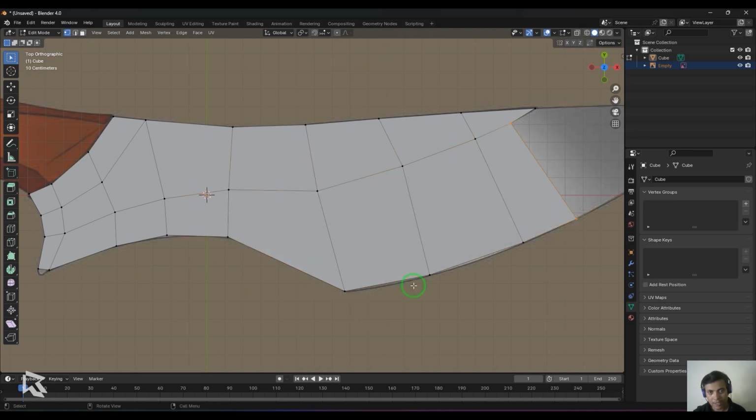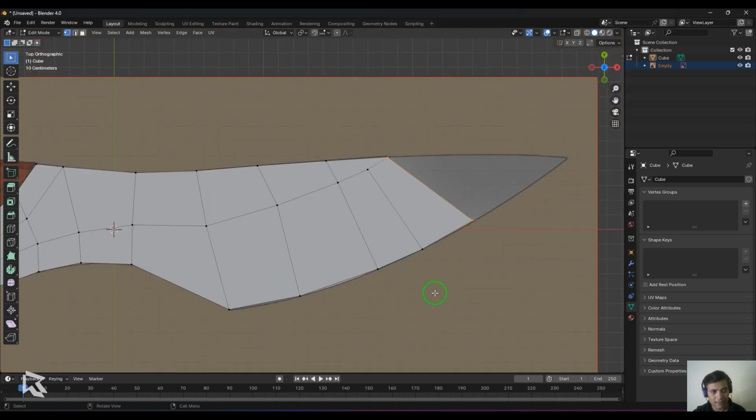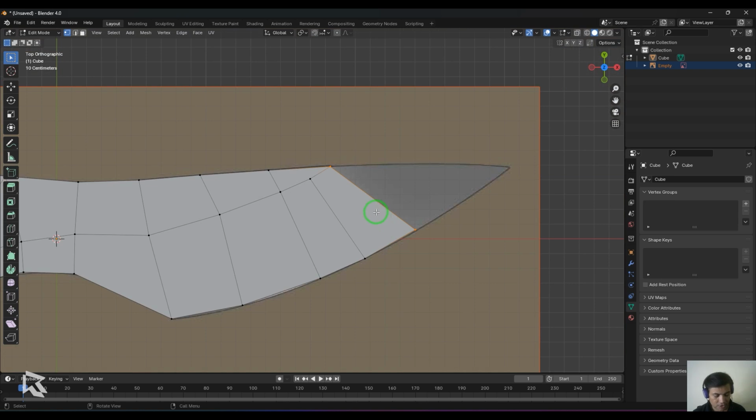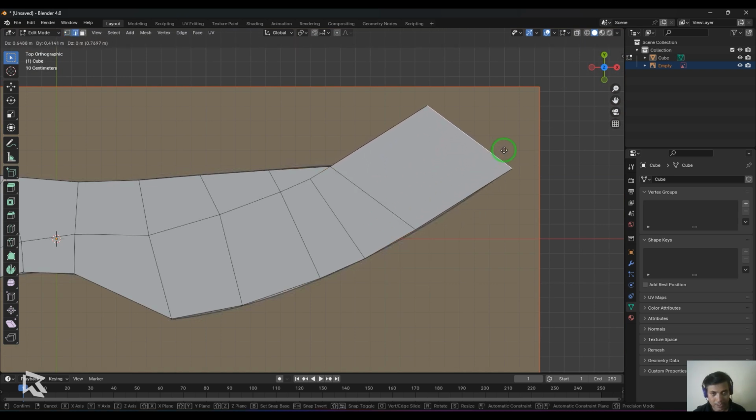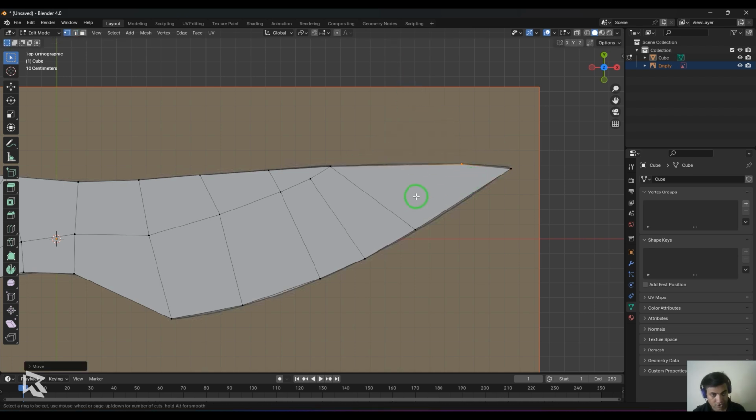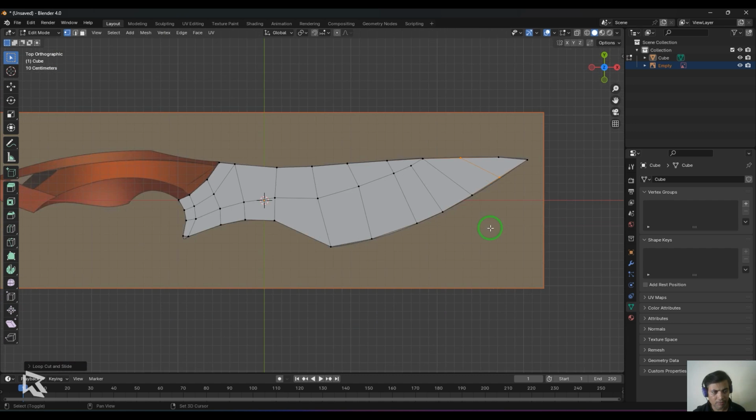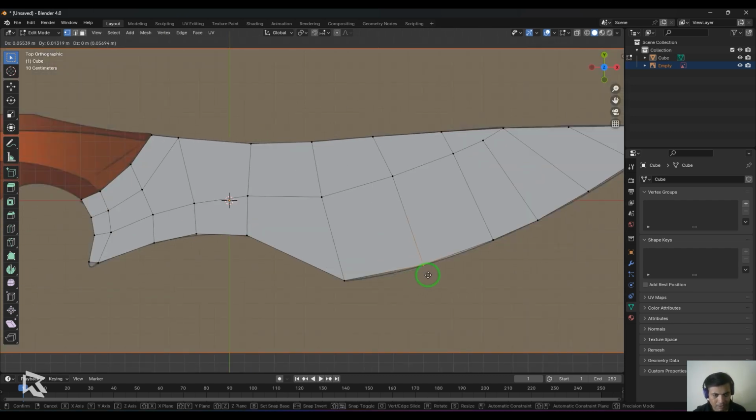And then it keeps building up those points like that. Once that is done, you can select this edge here. I can select that edge and then press E to extrude those points till there, and then press G and then press Ctrl R and then add the points. So you should be able to see I've not compromised in terms of triangles here. Maybe sometimes that is acceptable, but here luckily I didn't have any issues.